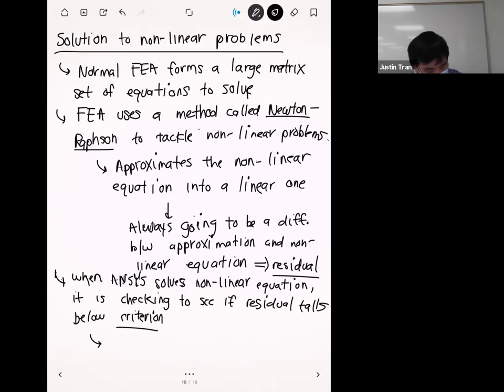And you can actually check this. And so, as your nonlinear equation is being solved, and honestly, sometimes when you solve a nonlinear equation, you're going to have a lot of free time because it's going to take a while to solve. But you can check its progress. And so if you go to solution information, right? So this is another tab that's in your ANSYS Mechanical workspace. Okay. And then you have two options.